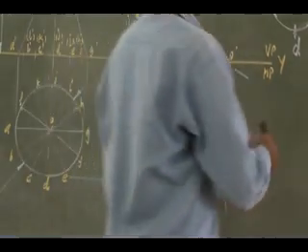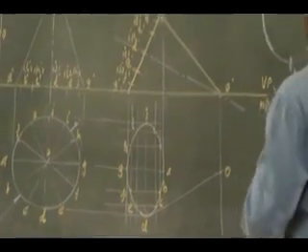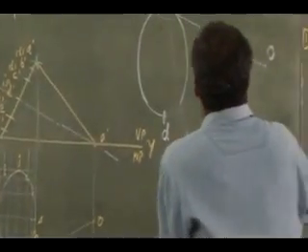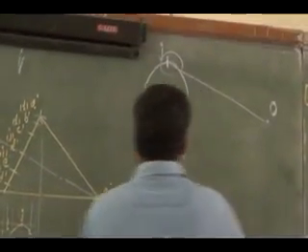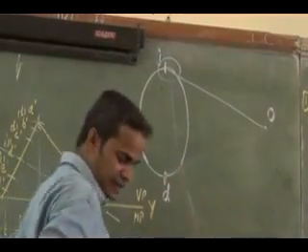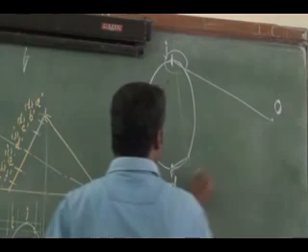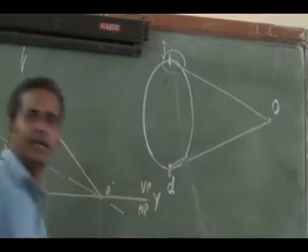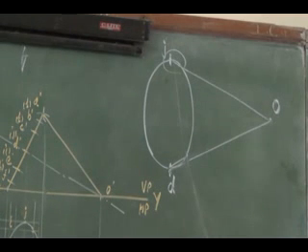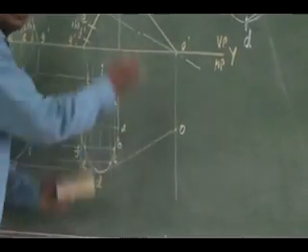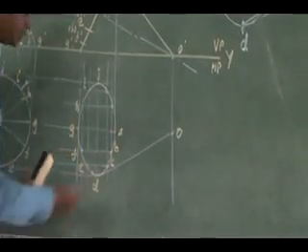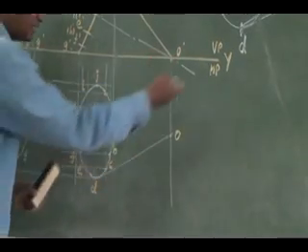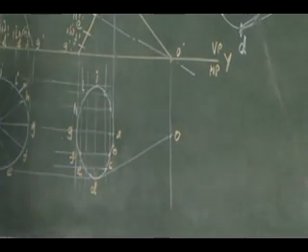See here, tangentially I have to connect it to the apex. From this ellipse, wherever it meets tangentially, that is the location where the tangent line has to meet it. You should not join from the base corner; the extreme slant line should tangentially meet the ellipse.